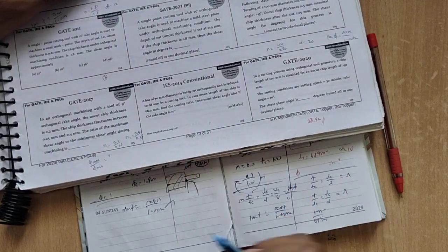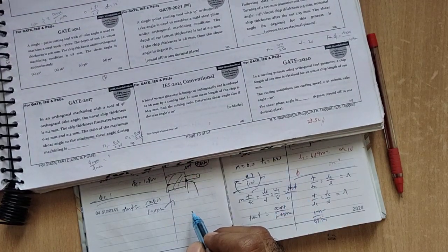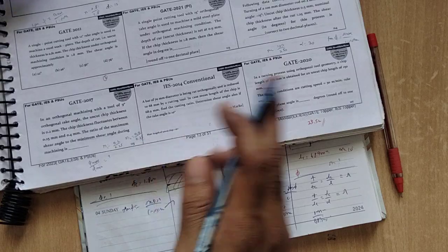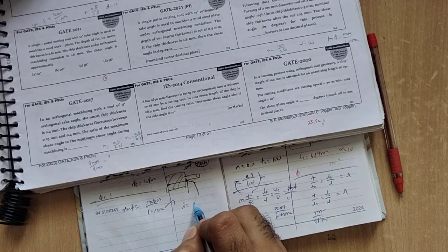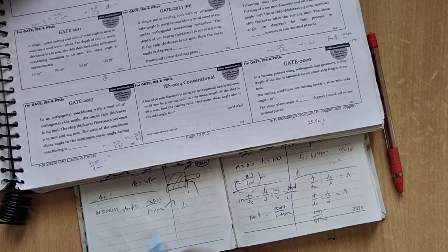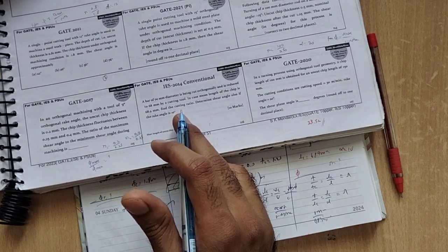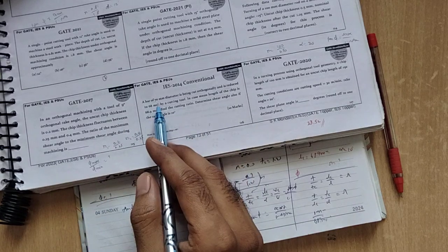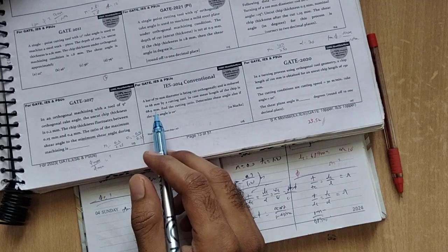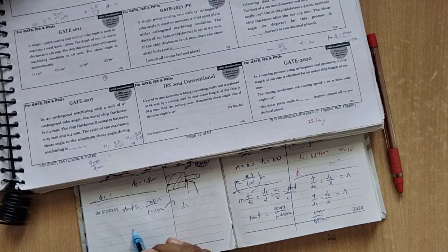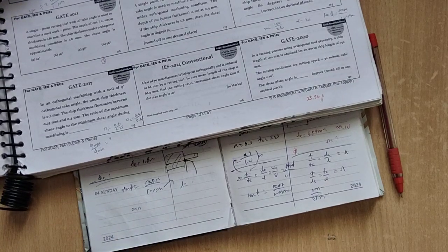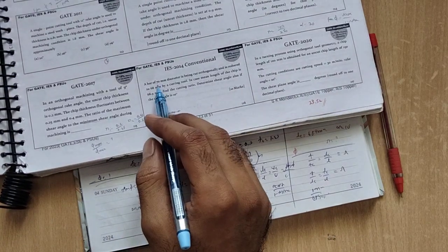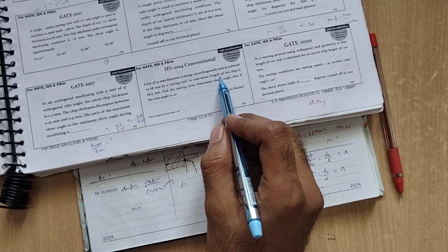So you can see what I just told, length of chip is 68.9, and the length of the entire thing is how much? Only 69. So they just took it in an average format. So L will be how much? This one is the length of chip, and this one 2 pi r, where r is the radius. So what they have done here is, this is a mean length of chip, not a direct length of chip.